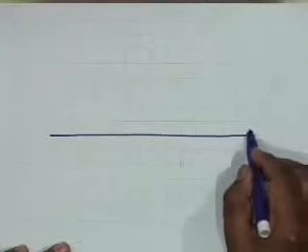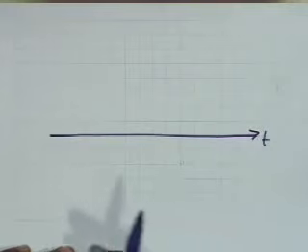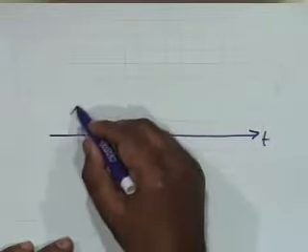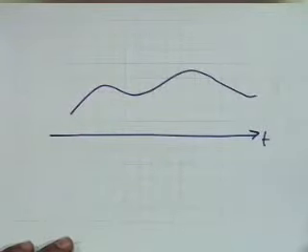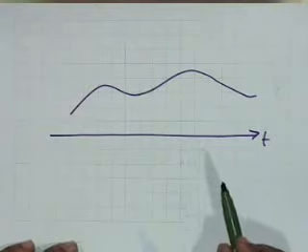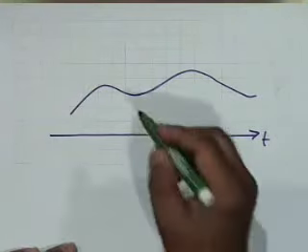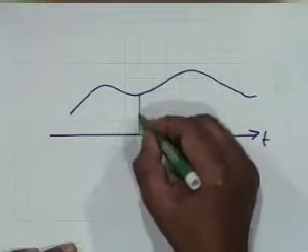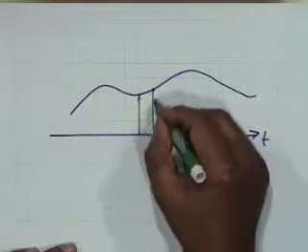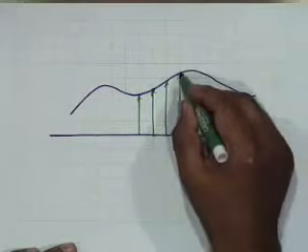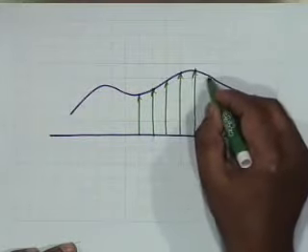But before that, let's look at some signals just to convince ourselves that sampling has to be a disciplined phenomenon. Let's say we have a signal like this, and we sample it by means of, we'll look at the sampling process a little later, an impulse train. So what we are doing is multiplying this x of t by an impulse train like this.